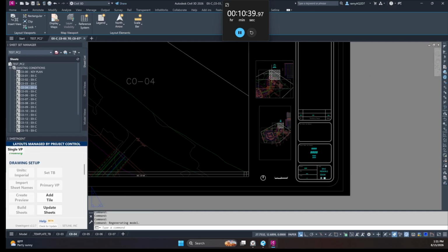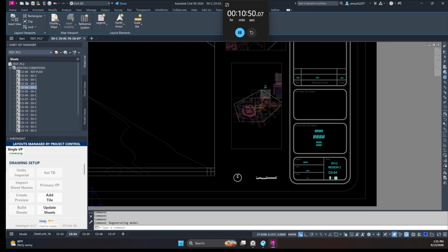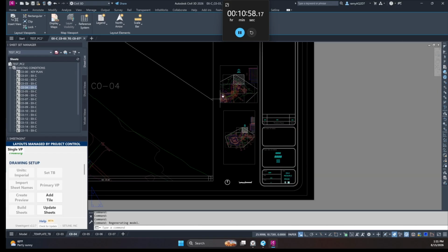So you can see 2 different zooms. This is region 2, and you can see it created a small key map for the zone, which in our case is the region 2 zone, and you still have the overall key plan key map, which showcases our entire project. These are the two things that are really helpful. It helps large projects keep it focused. A lot of contractors prefer this, so they know where they are zoomed in and where they are as an entire project.